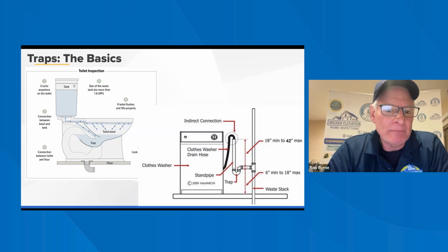When you flush the bowl, if you get gurgling, there's most likely a problem with the venting system. So you can comment on that. It could be problems with the sewer line, those types of things. When you flush the bowl, it should flush down nicely and smooth. If it starts gurgling towards the end, same thing with a bathtub. When you fill up the tub and you release it, you watch it as it's going down. Sometimes you'll see air bubbles backing up. There's a venting problem that you would definitely call out.